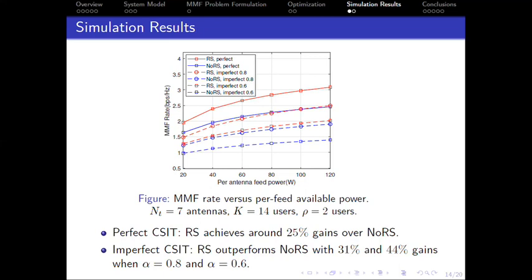Accordingly, the advantage of using RS in terrestrial networks is still observed in multibeam satellite systems. By partially decoding the interference and partially treating the interference as noise, rate-splitting is more robust to CSIT uncertainty and the overloaded regime. Such benefit exactly tackles the challenges of multibeam satellite communications.